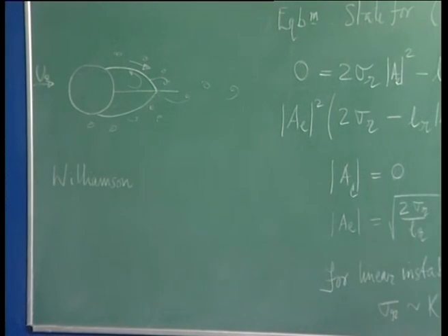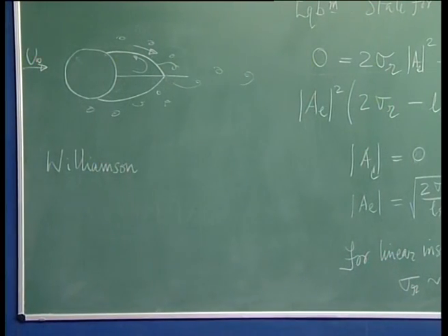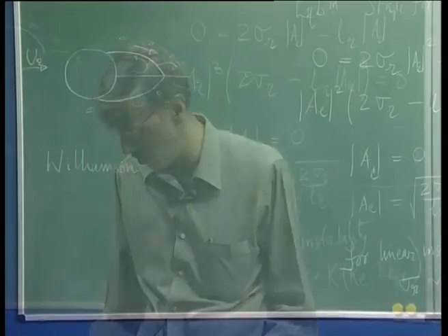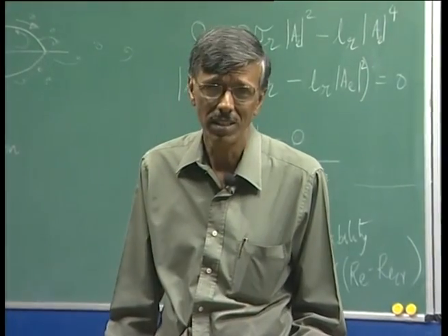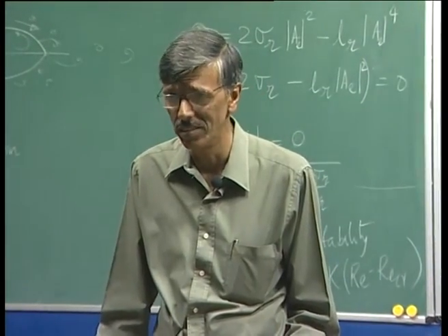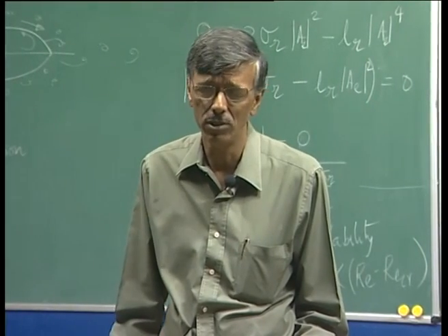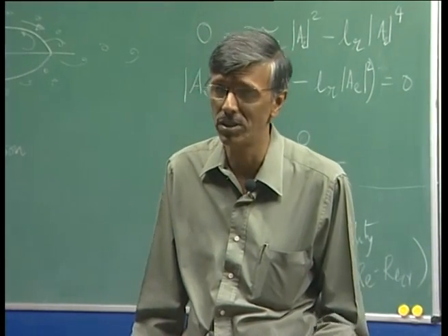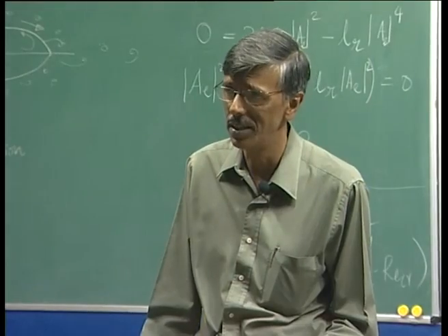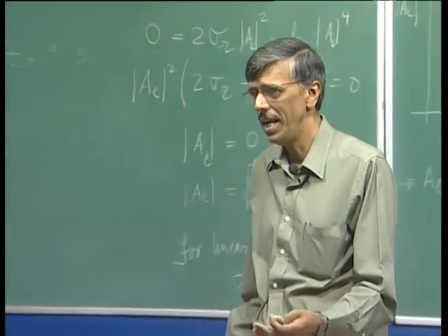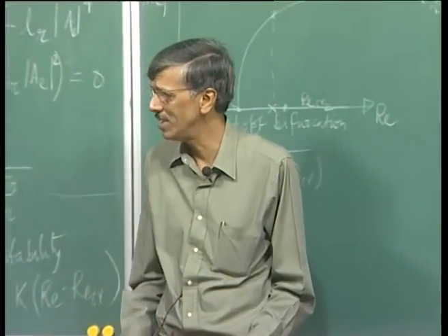He has demonstrated experimentally by doing very careful experiments that 3-dimensional instability effects show up for a Reynolds number which is above something like 180, 200 in that range.